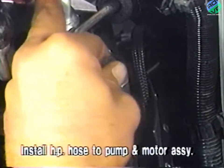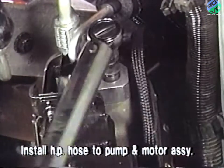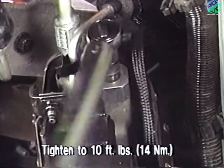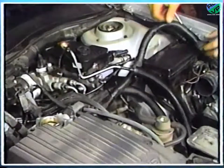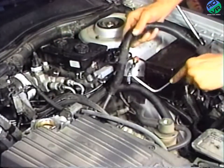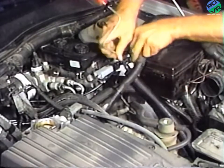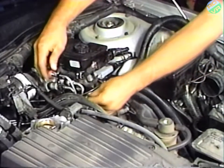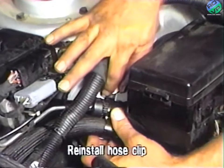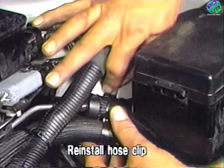Next, install the connector block end of the supplied high-pressure hose to the pump face with the banjo bolt and tighten the bolt to 10 foot-pounds or 14 Newton-meters torque. Next, lower the vehicle and finish routing the high-pressure hose to the hydraulic assembly. Now, reinstall the high and low pressure hoses in the brake hose clip and reinstall the clip attaching bolt to the shock tower.